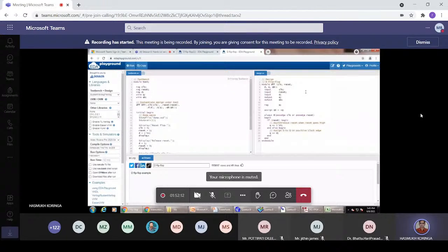Then declare the ports, input ports and output ports. Here it is sequential, so always is a procedural statement, so the output needs to be explicitly defined as a reg. By default, input and output are wire type. Then assign Q bar to QB, which is Q bar.